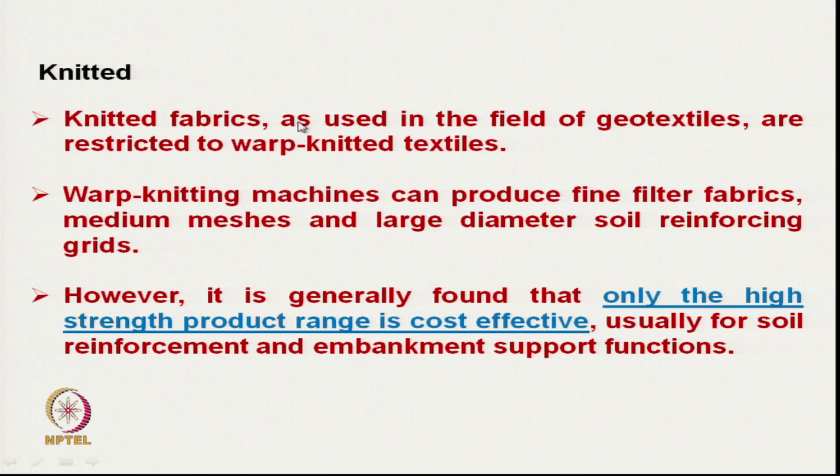Knitted fabrics as used in the field of geotextile are restricted to only warp knitted structures. As the warp knitted structures are expensive, only the high strength product range is used, where soil reinforcement and embankment support functions are needed. There we can use warp knitted structure.